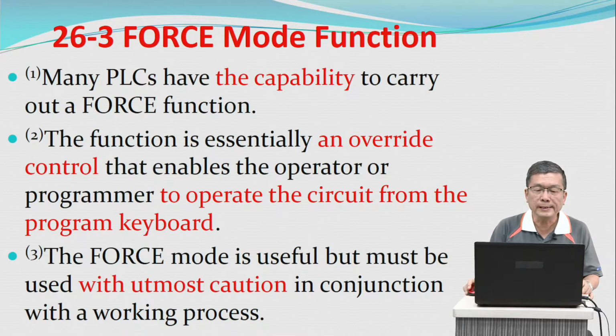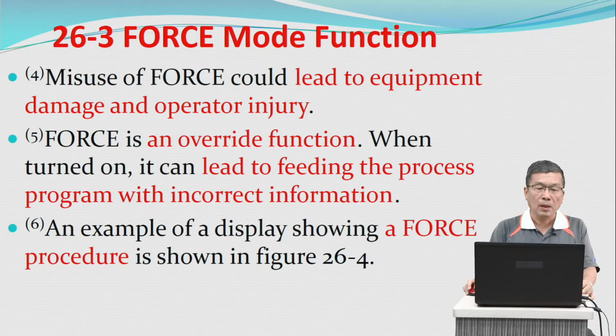The function is essentially an override control that enables the operator or programmer to operate the circuits from the program keyboard. The force mode is useful but must be used with utmost caution in conjunction with a working process. Misuse of force could lead to equipment damage and operator injury.